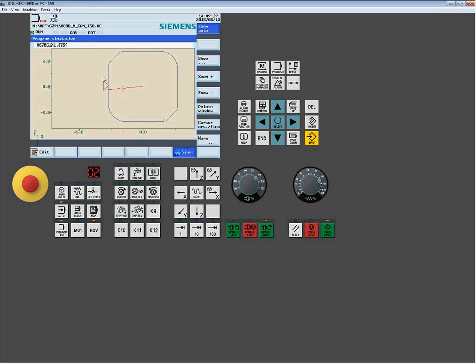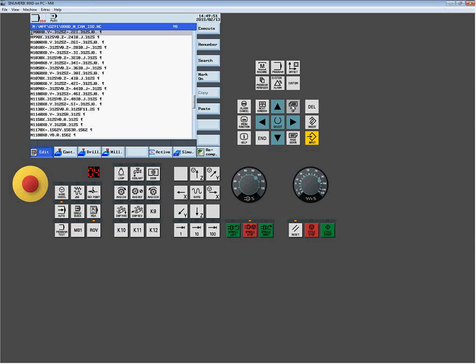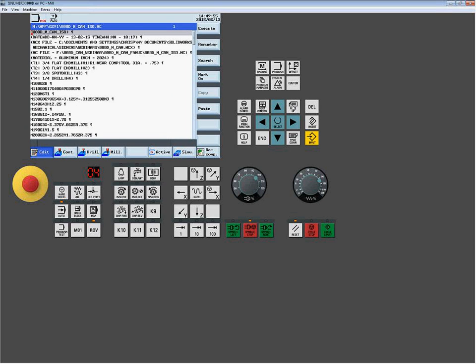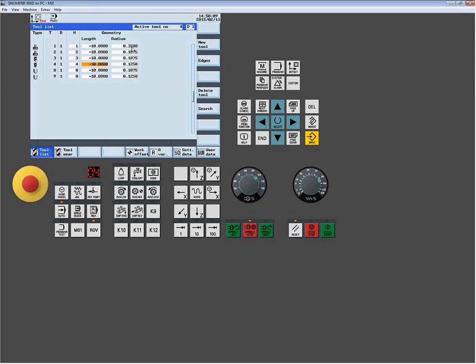Now, I see I get this heavy offset, nice big arc. That's because this is double compensating again, like we saw earlier. This program was written for cutter compensation with wear. So come down here to the line N170. There's my G41 cutter comp line. Well, because of that, just like we saw earlier, if I have a radius in my tool, I'm going to try to use it.